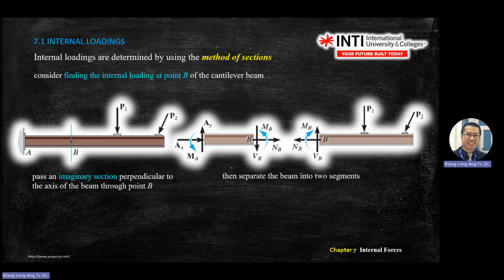So how do you determine the direction? If your A is clockwise, when this body has turned like this, this point will turn like this. This blue arrow will follow point A, because if you cut and then turn this one, this will follow this direction. And you need to cancel this one. So you copy this arrow and flip it, and it will become a clockwise direction. You don't touch the external force.